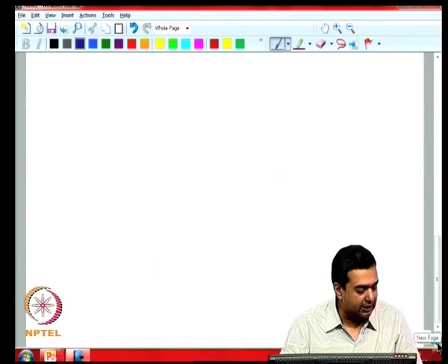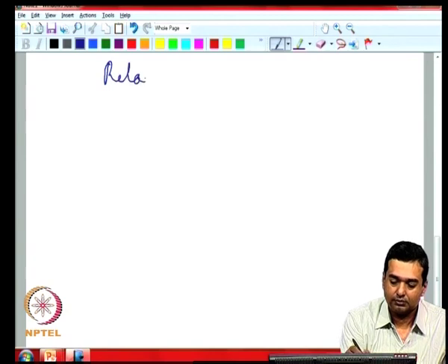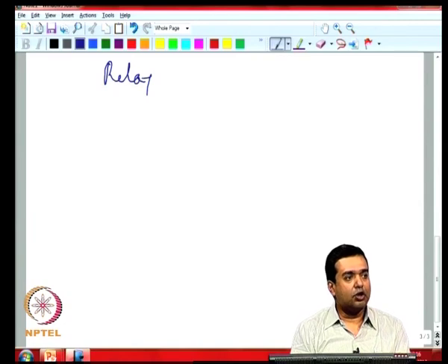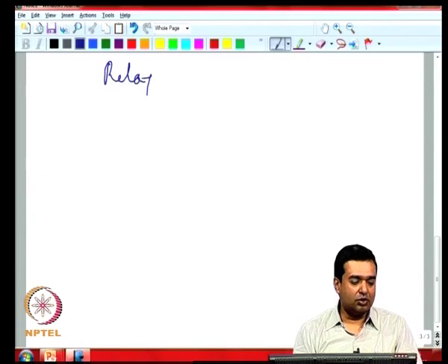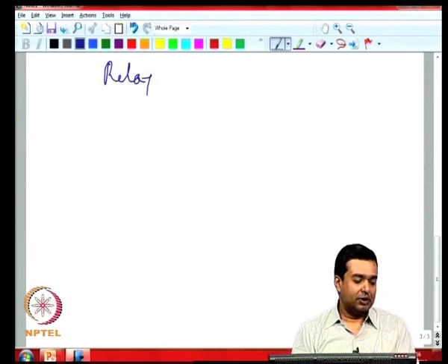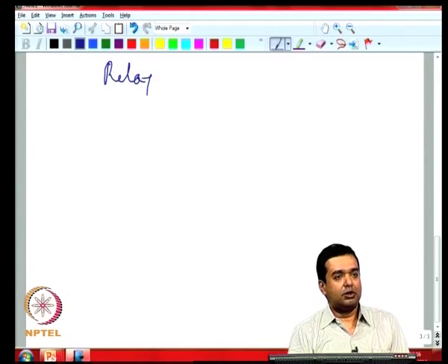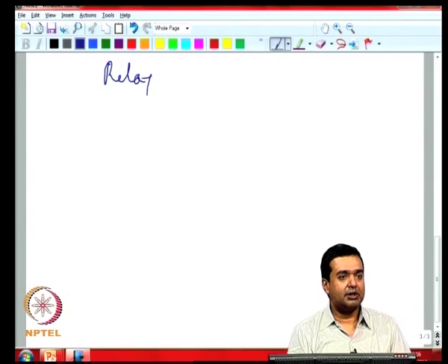If you look at a relay, you can think about the relay as essentially the control package which governs whether the switch needs to open or close, and for overcurrent protection you are looking at an overcurrent relay. So, essentially the relay is a device which initiates whether to trip the breaker, or some breakers have abilities to reclose or close. So, the relays can actually give such commands to a circuit breaker.